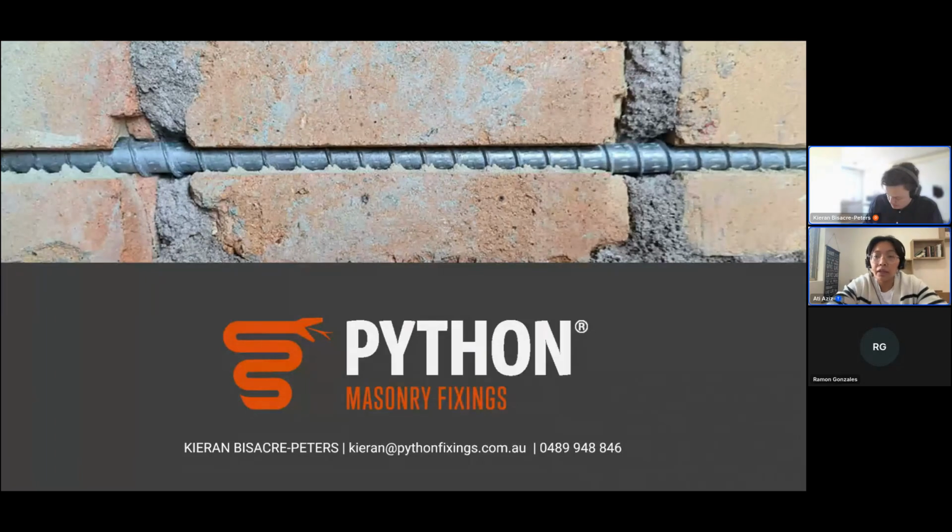Sorry, Matthew. Yep. Does Python Anchor have seismic ETA C2 and pin fixings with seismic ETA? Good question. So in masonry, C2, the ETAs really come from the concrete world, and there's no such requirement for having an ETA or C2 rating in masonry substrates for retrofitting them. So it's just not a requirement and not needed. However, we do actually have another anchor, which is specifically for hollow core floors, unrelated to the masonry work that we do, and that does have a C2 rating.